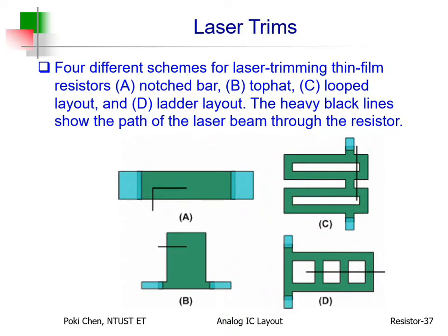Laser trimming. It was used in the past. Nowadays, forget about it. Okay? Because it is too expensive, to be honest. And after laser trimming, sometimes it would go wrong again. Those are the two main reasons we wouldn't like to apply it nowadays. But the concept is still good.